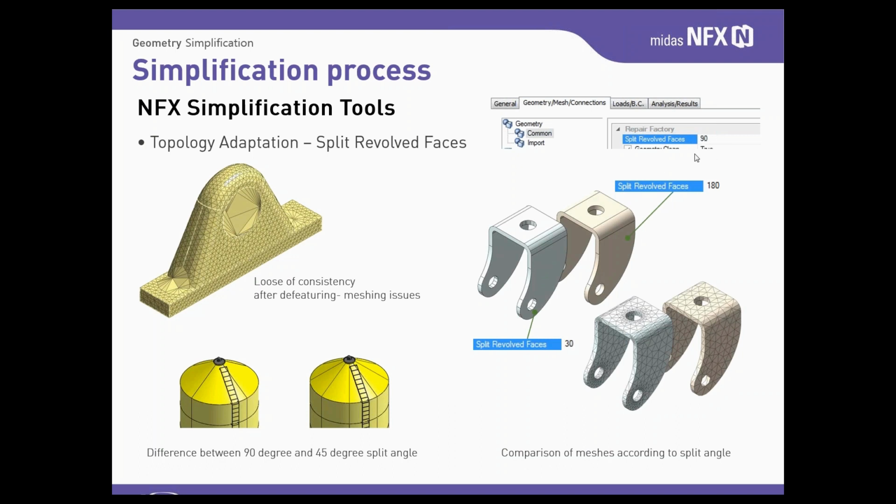So this is really important for us since the topology of imported geometry will differ depending on this setting. The default value is 90 degrees, but for some cases, and simplification is one of them, this value can be changed, as I did for my example where I specified 180 degrees. I made this to allow me to delete edges.